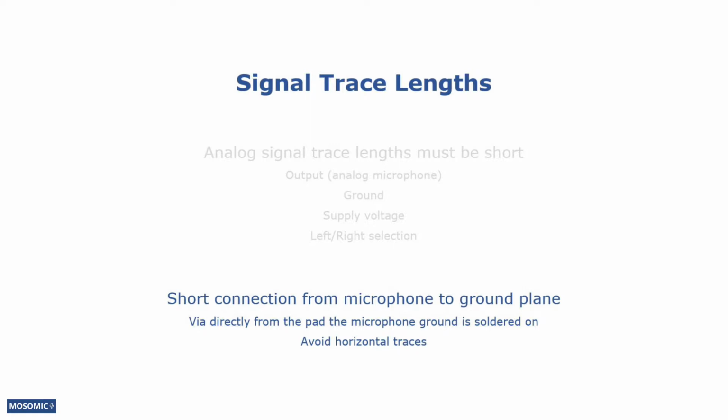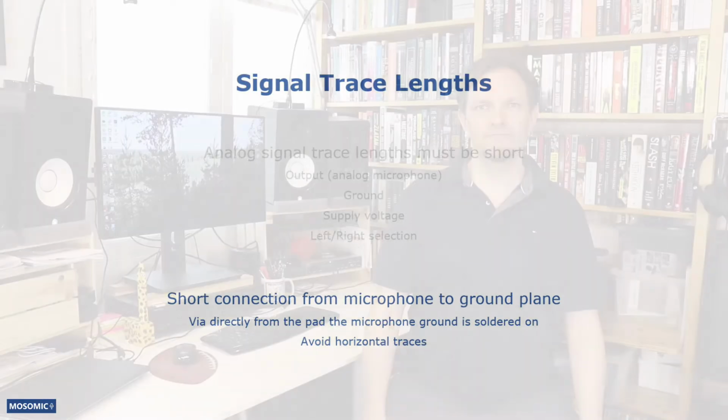Just like with the connections from filtering capacitors to the power source, traces in the XY plane of the device circuit board should be avoided. Sometimes short traces are not possible. If the microphone output line is long, a digital interface should be considered.